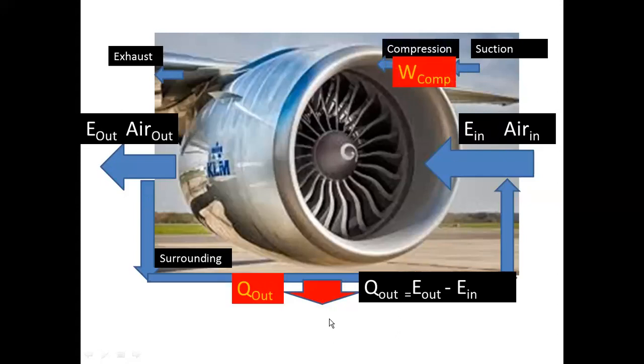And it is compressed, same as in diesel engines, even petrol engines, you have to compress it. One reason is that compression makes your machine smaller, compact. And the other point is that compression raises the temperature of the working fluid, the air, to the ignition point of the fuel, which means compressed air enters the combustion chamber, interacts with the fuel, and there is a huge energy coming out.